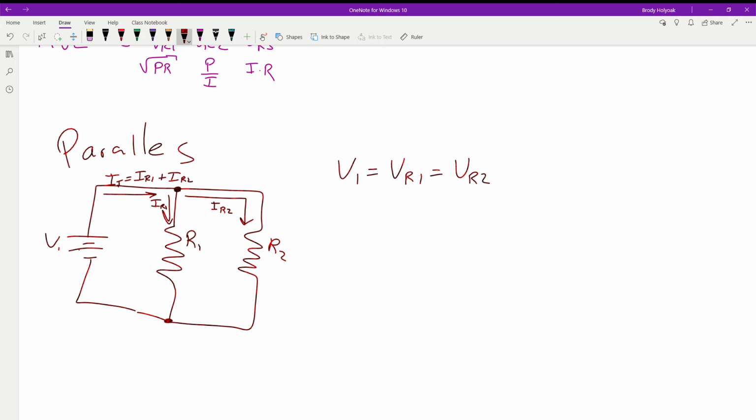So everything that you have is going to be wired in parallel with each other. They need the same voltage. That's why, if you look, no matter what plug you go to in your house or into the room, when you measure it, it's 120 volts AC, every single one of them, because every outlet is shared in parallel. So the idea behind this,